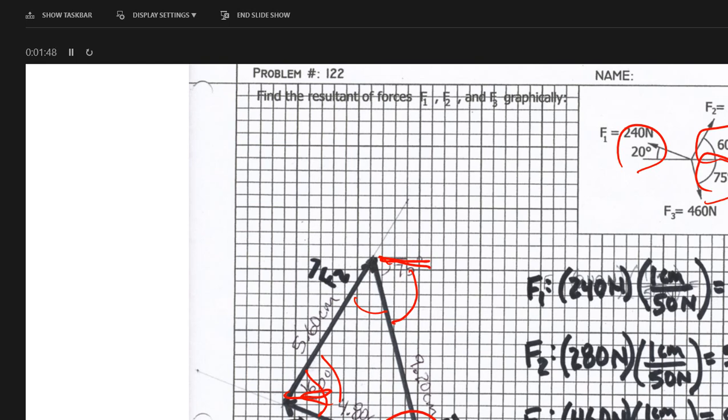So that goes from the starting point, which is right here, if my pen will work, there we go, to the end right there. There's the resultant. Yes? So my result overlapped. And to find the angle, would the angle be the angle inside? Well, you can define the angle really however you wish. The resultant went like that, and I agree, this one was a little messy because there's an overlap there. It's kind of hard to read. But the angle is always with the horizontal. That's how we reference angles. If you're clear in the angle you measure and showing what line it's from, it should be fine, if that answers your question.